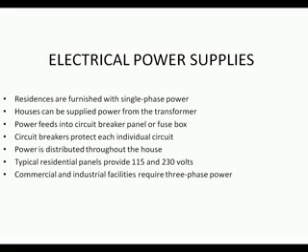The motor may start with unequal pressures across it, like in a refrigeration system. Small fans do not require much starting torque, so in a refrigeration system, the evaporator fans might not require much starting torque and therefore will be a different type of motor.